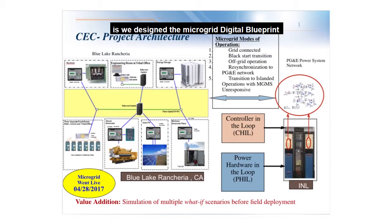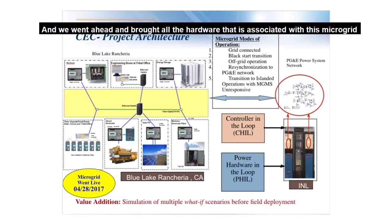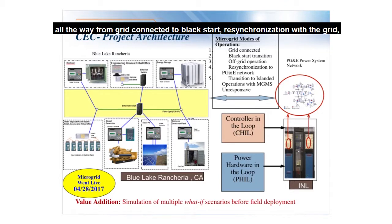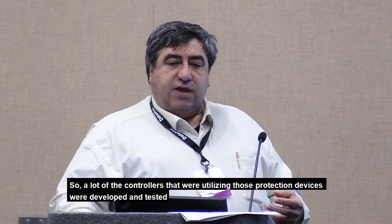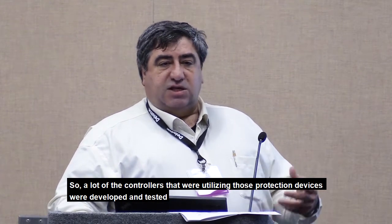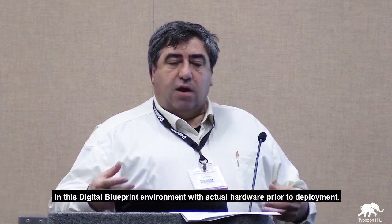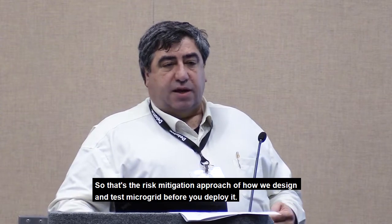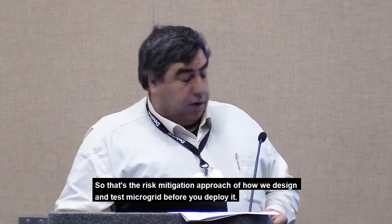So what we did is we designed the microgrid as a digital blueprint in a real-time simulation environment, and we brought in all the hardware associated with this microgrid and tested it under different kinds of grid scenarios, all the way from grid connect to black start, resynchronization with the grid, and what-if scenarios, in order to test the resiliency before we deployed it. A lot of the controllers utilized in those protection devices were developed and tested in this digital blueprint environment with actual hardware prior to deploying it. So that's a risk mitigation approach for how we design and test a microgrid before you deploy it.